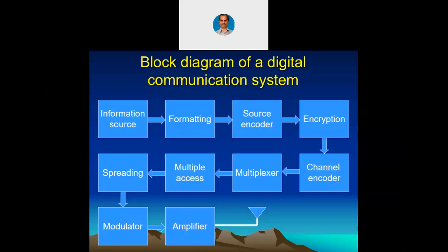You would have worked with amplifiers in the AEC lab when you actually connected a BJT or a JFET and connected resistors as biasing components, and you would have measured the gain and bandwidth for a single stage amplifier. Or you would have done a multi-stage amplifier simulation also using PSpice. But you used audio frequency amplification there. Now what we are talking about is radio frequency amplification. For example, if your cell phone is using 2.4 gigahertz as a carrier wave, now in the cell phone you should have an amplifier which is working with 2.4 gigahertz.